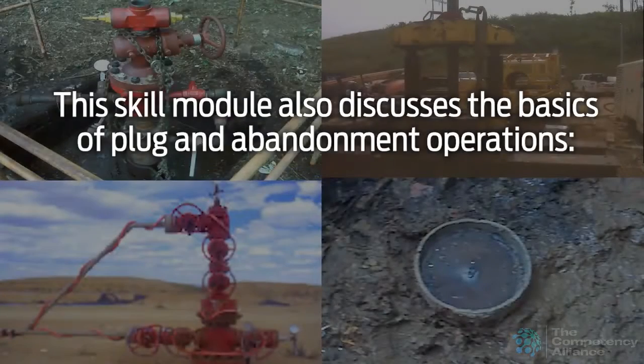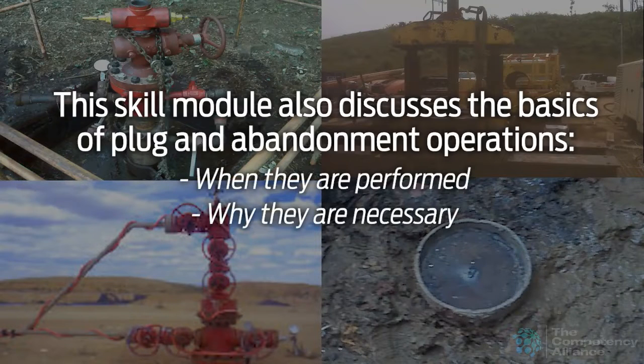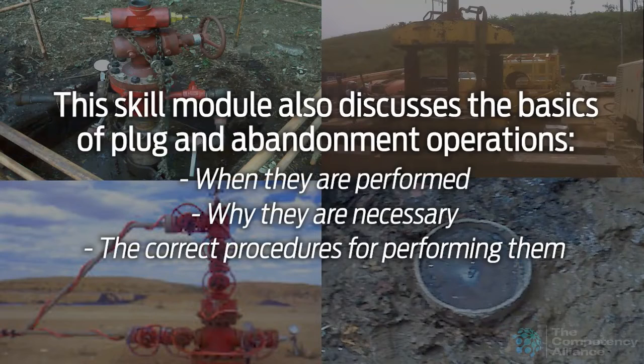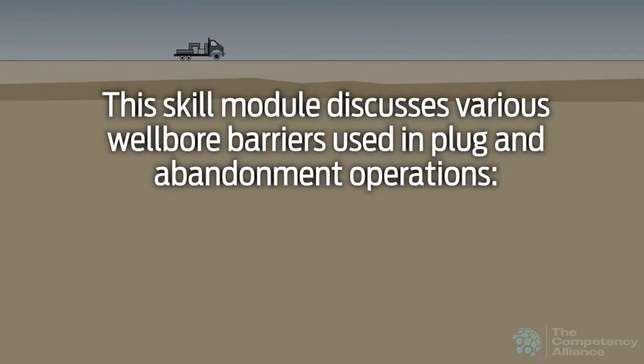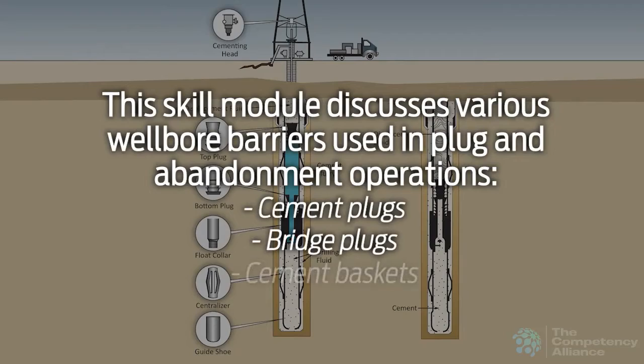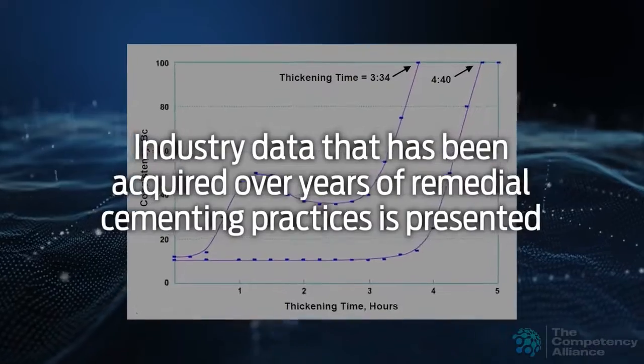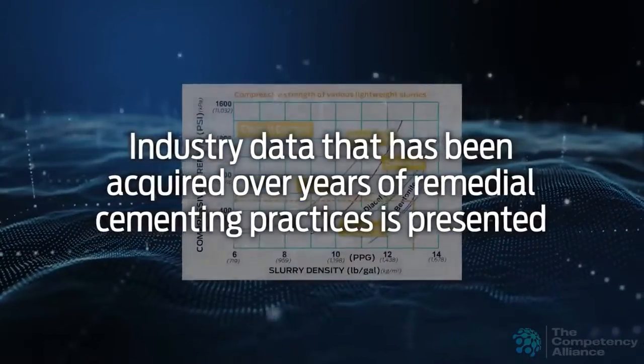This module also discusses the basics of plug and abandonment operations, when they are performed, why they are necessary, and the correct procedures for performing them. This module discusses various wellbore barriers used in plug and abandonment operations, such as cement plugs, bridge plugs, and cement baskets. Industry data that has been acquired over years of remedial cementing practices is presented.